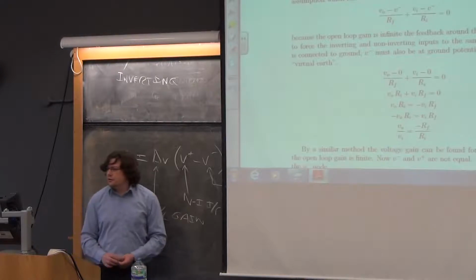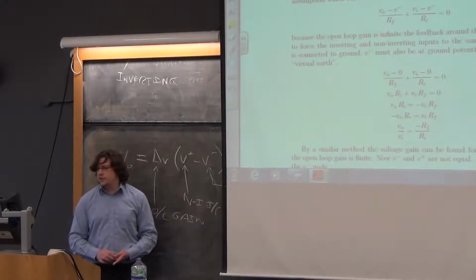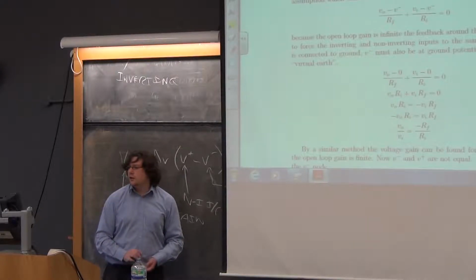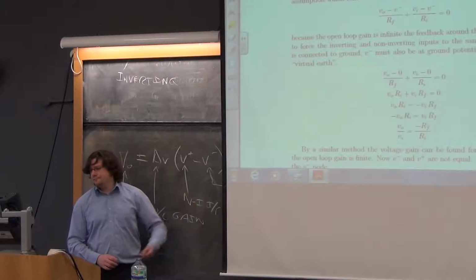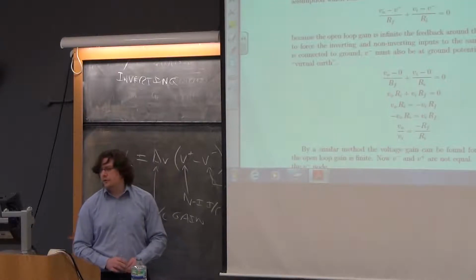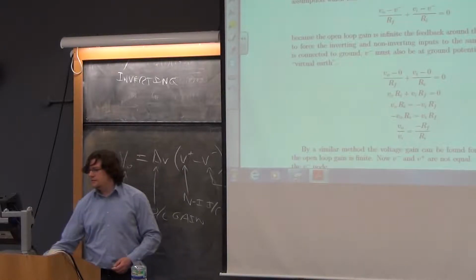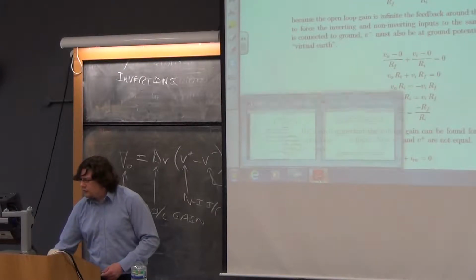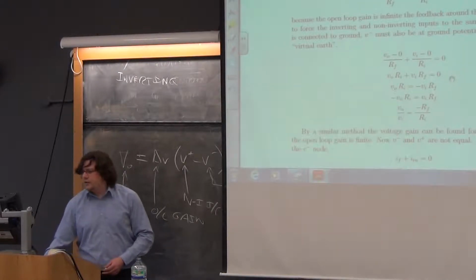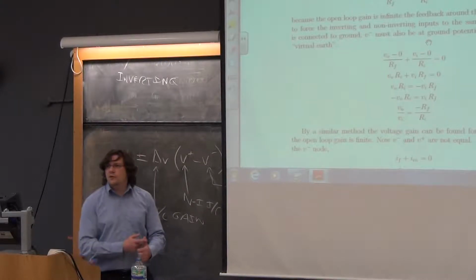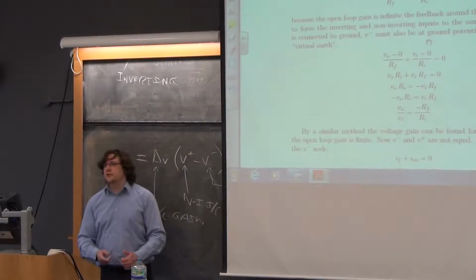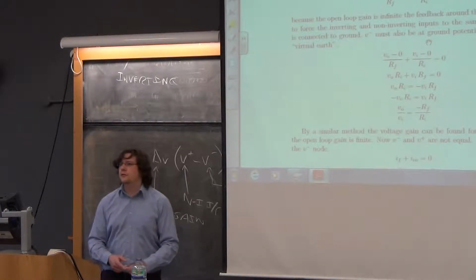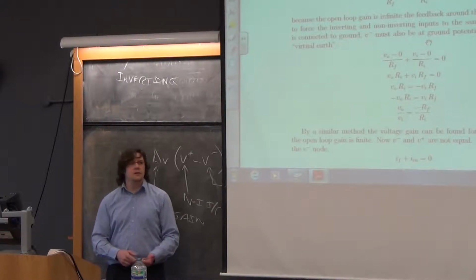So yeah, you sub in the voltages and the resistances and equate it all to 0, so essentially 31, you've subbed in V and R into 30, and then you do some maths, and you end up with minus RF over RN. And the maths is your own business pretty much. So you get 3 marks. Now I wouldn't be giving out a mark for every line. It's a mark for the first bit that says you sum the currents because that's conceptual, a mark for knowing you sub in the voltages because that's the use of Ohm's law, and a mark for the right answer.